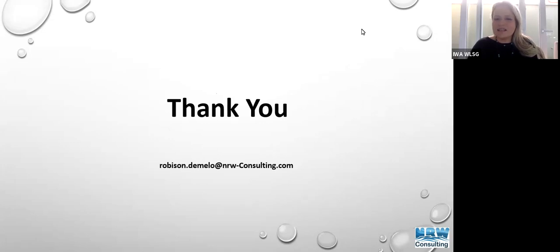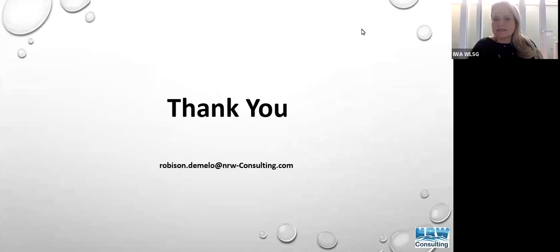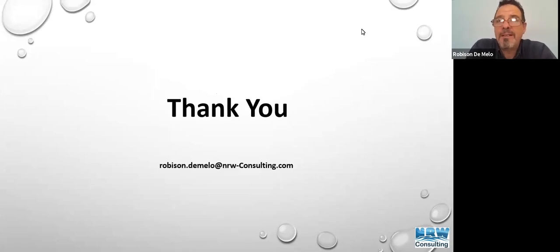Hi, can you calculate N1 in intermittent systems? Yeah, intermittent systems. I would say, well, you can. However, it depends. You just have to remember one thing: to identify the N1, you have to perform the drop test during the minimum night flow.